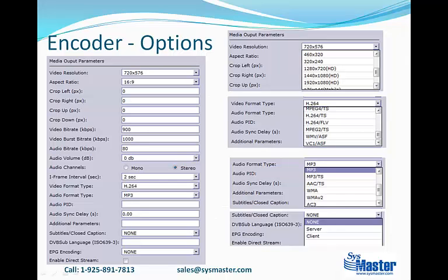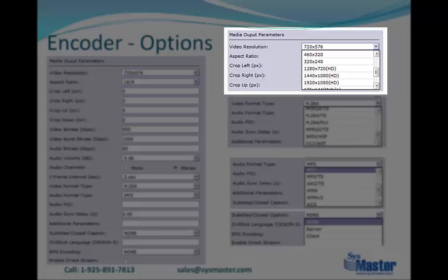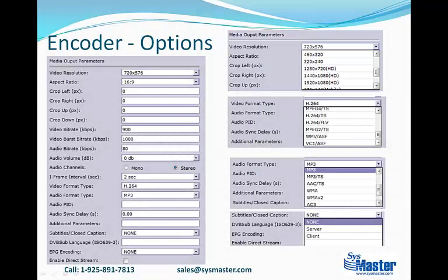In addition to offering a variety of inputs, our encoders offer several output options, different resolutions to cater to all screen sizes: smartphones, tablets, and several SD and HD resolutions for standard television sets. The video bitrate can be adjusted for different screen resolutions and network considerations, and can now be as low as 350 kbps for lower resolutions. To take care of fast action video, we have the adjustable burst rate feature.